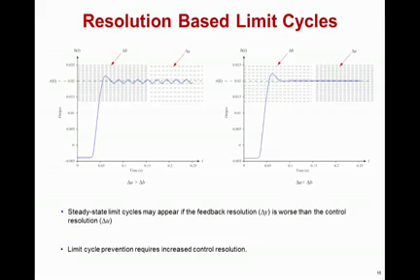Delta U shows the resolution capabilities of the PWM module. As shown in the first graph, if you have a higher resolution ADC than the resolution of your output, then you see oscillations on the output voltage. This is due to the fact that the ADC is capable of measuring the output voltage more closely than the PWM is able to actually regulate that output voltage.